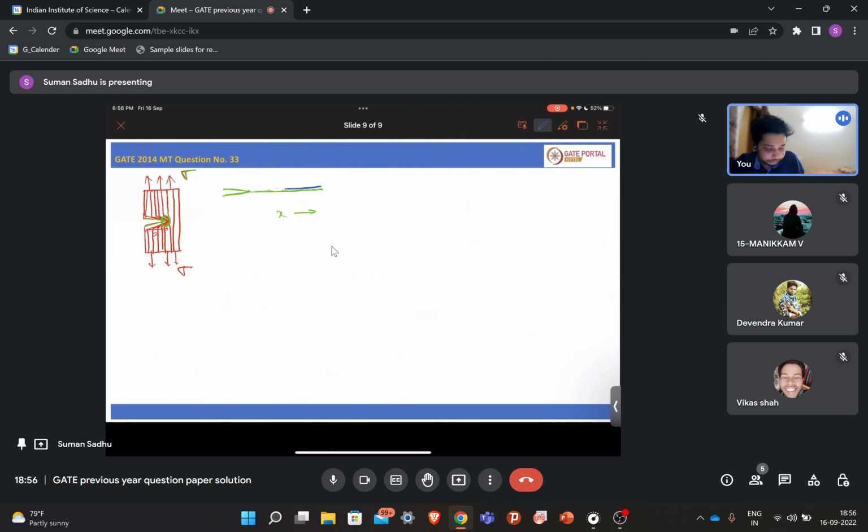But as you are approaching the crack, what will happen? Your stress suddenly increases because of the stress concentration. Very near the tip of your crack, the stress will be sigma max, the maximum stress it can reach. And far away, the stress will be the sigma you are applying. So what will happen after some time? Now your crack is sharp, but your stress is higher at this point.